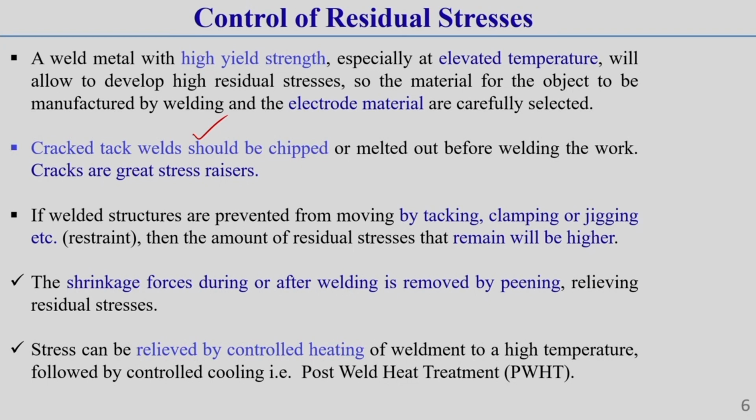We know we can minimize this residual stress by introducing opposing types of stresses. In the weld zone, in the case of structural steel, generally a tensile type of stress is developed. So, if we can develop some compressive stress there, then we can nullify, or mitigate, or minimize the residual stress.